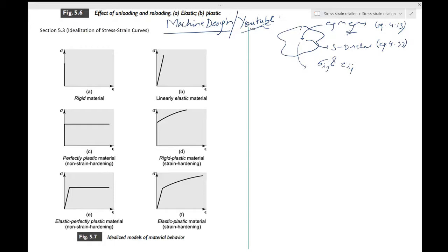You should be able to do it practically for any point in this solid. These relations for each differential element comprise the three steps. Remember the steps 2.1: the strain displacement relationship was about the deformation in the compatibility equation, and the third relation was between force and deformation, in this case the relationship between stress and strain.